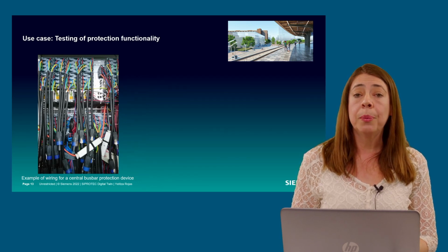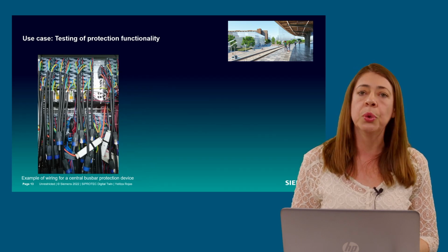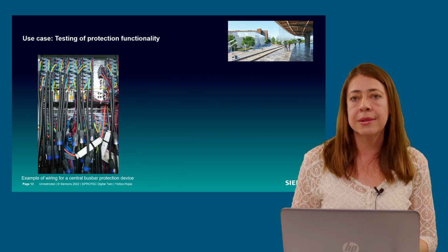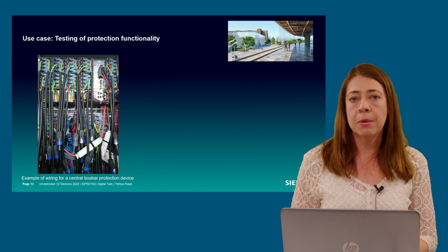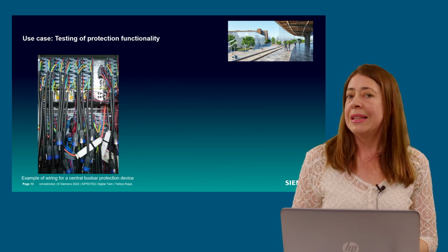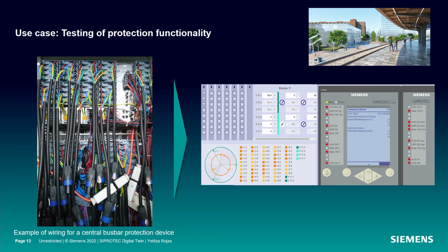The availability of the proper secondary injection equipment, the device itself with all the required terminals, the wiring of currents, signals, and trips, all these topics cost time, space, effort, and money. The same tests and even more can be done in the virtual environment. No hardware is needed.